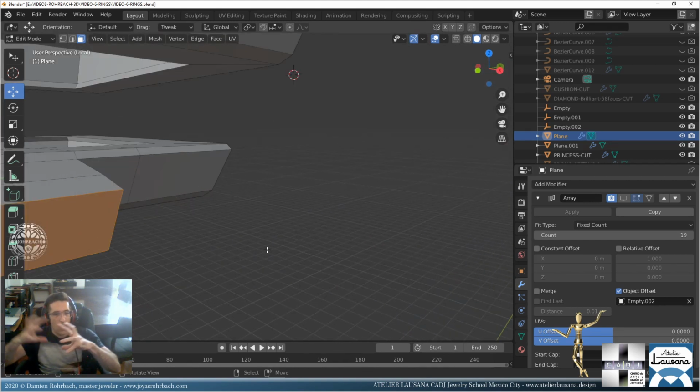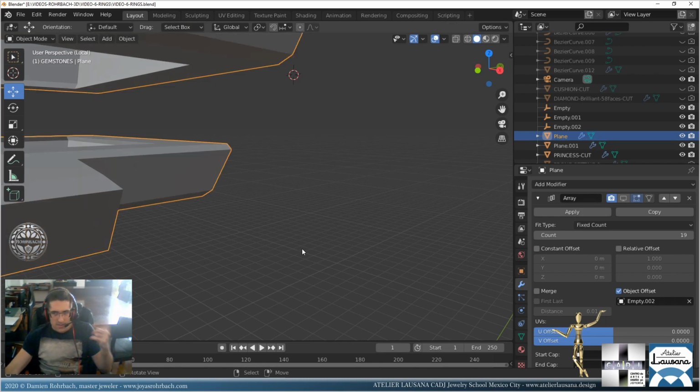So every overlapping object with the next object is going to create an entire solid, which is what you need for printing. That's the basic goal when modeling for printing: you want one solid object without loose open edges or things like that. So this is correct.